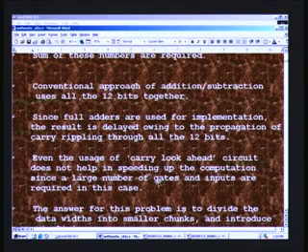If you test it against a ripple carry of the same width, on an FPGA platform or an ASIC platform using the Synopsys DC compiler, you will get a figure which is far less than even the ordinary ripple carry, and that is the reason why this carry look ahead circuit does not really help.